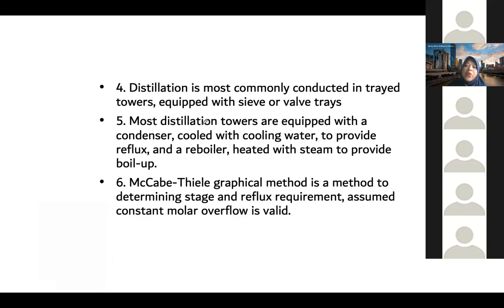Most distillation towers are equipped with a condenser, cooled with cooling water, to provide reflux, and also a reboiler, heated with steam, to provide boil-up. The McCabe-Thiele graphical method is a method for determining stage and reflux requirements, and it assumes that constant molar overflow is valid.